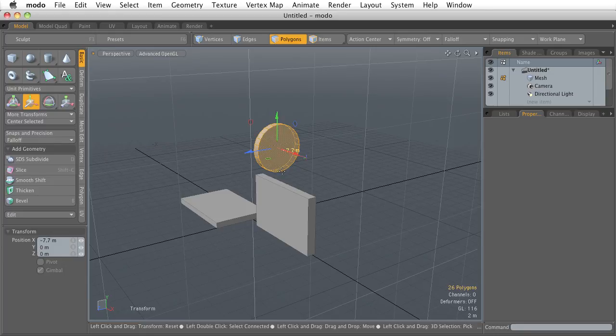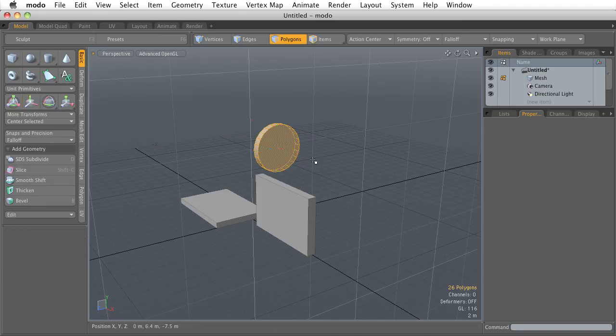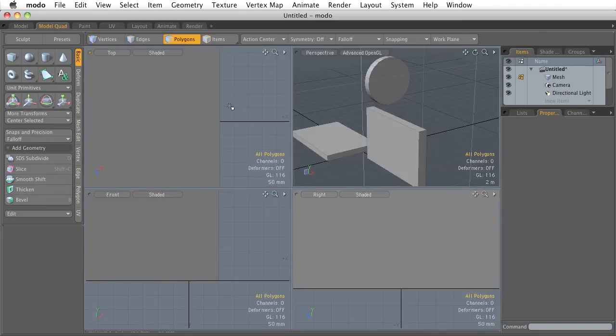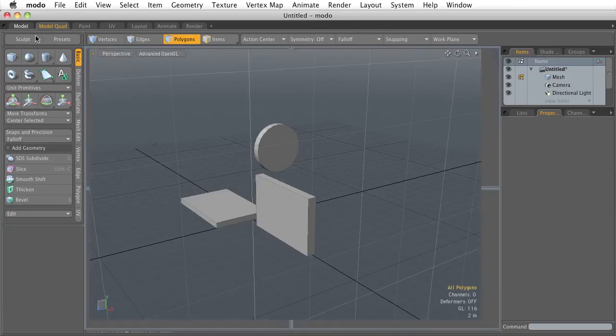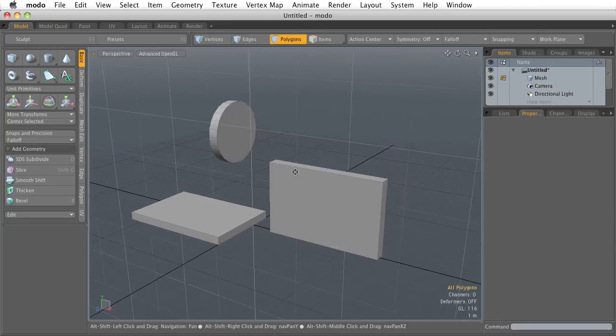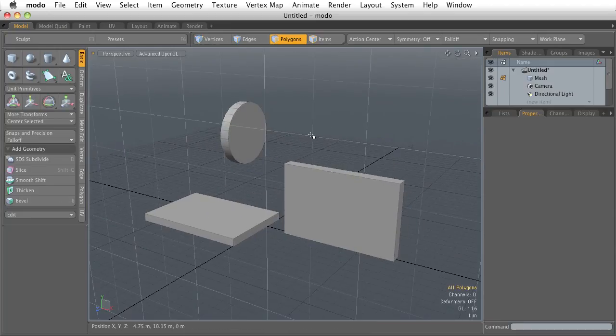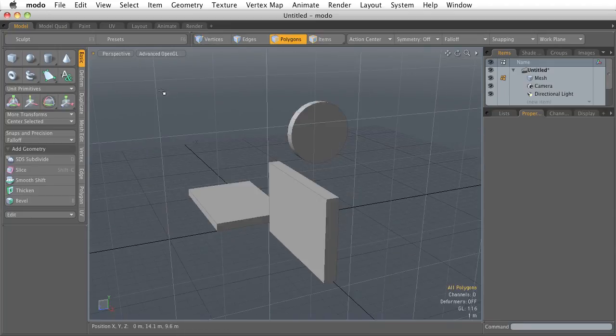I love the workplane. It just makes things so fast and so easy. In other modeling applications, you have to go over to something like the quad view to accurately place and create items along a series of axes. Well, in Modo, the developers are incredibly intelligent, and they've created this workplane to let us use just one viewport. So jump into using the workplane. I think you're going to find it's extraordinarily helpful.